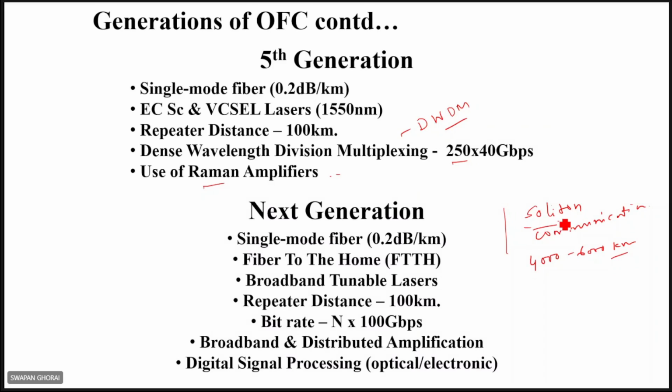In case of fiber, dispersion is there, and we'll see it. Dispersion means that if you launch some pulse, then this pulse shape will be broadened. That is because of dispersion, right? And there is another effect in optical fibers, which is nonlinearity. Because of nonlinearity, the spectrum through the optical fiber will increase, I mean, the pulse shape will become narrow, because of the generation of new frequencies.